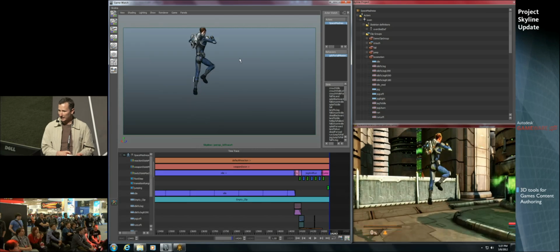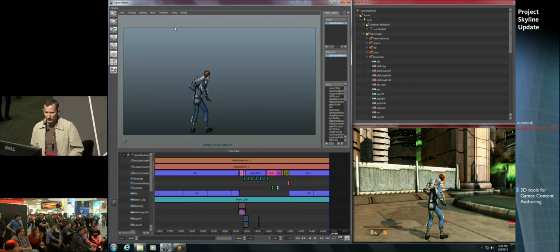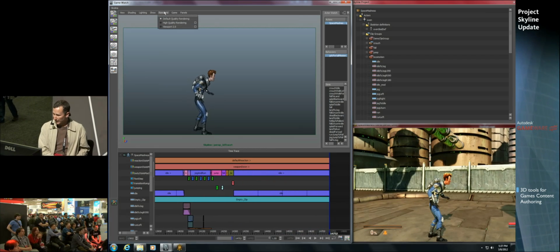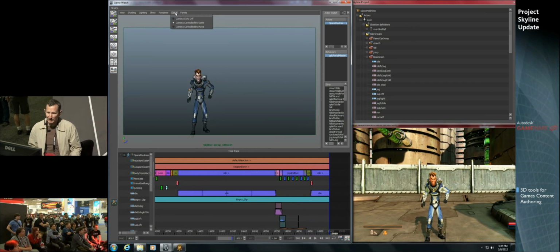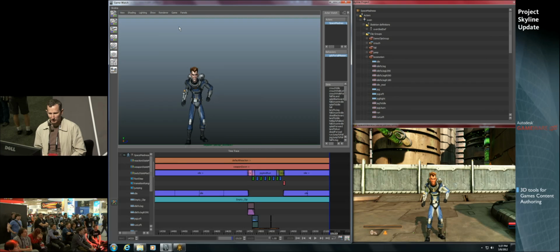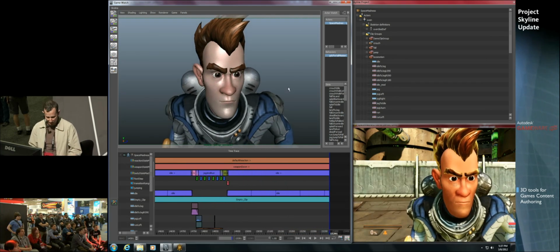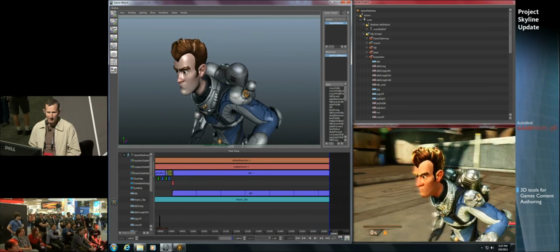So as I jump in the game, it's going to trigger a jump in Maya. What I want to do now is look at the character from a Maya point of view. Previously, I was driving the character with the gamepad that I'm using to drive it. I can switch over into a Maya-centric mode, and that allows me to, for instance, select the face and frame in on that face, and then use the Maya camera to start to look at my character and analyze the animation.